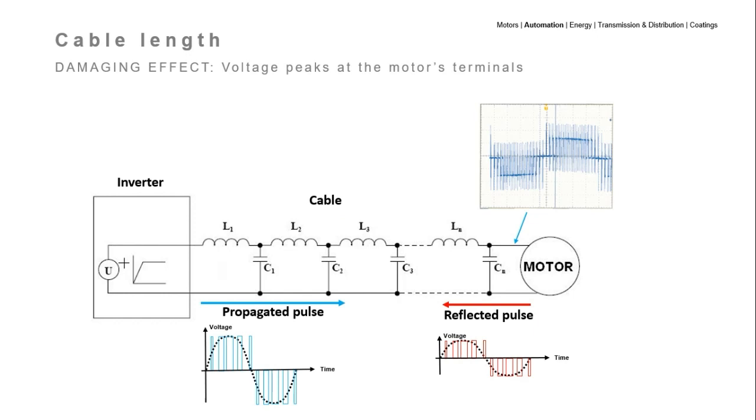The cable can be considered a transmission line with impedances distributed in sections of inductance and capacitance, series and parallel connected. At each pulse, the inverter delivers energy to the cable, charging those reactive elements. The signal reaches the motor through the cable and is partially reflected, causing overvoltage, since the high-frequency impedance at the motor input is greater than the impedance of the cable.